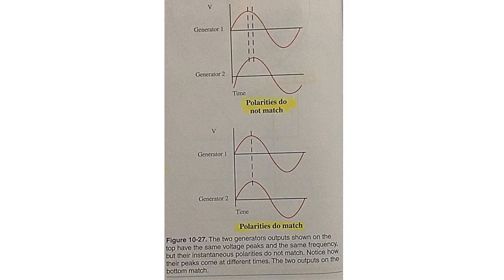If the voltages of two parallel generators do not match, they can be made to match by adjusting one of the field pole rheostats. A slightly trickier part of parallel generators is matching the correct frequencies of the two generators. The frequency, or hertz, of each generator can be compared using a frequency meter. If the frequencies do not match, we need to speed up or slow down one of the generators until they match.